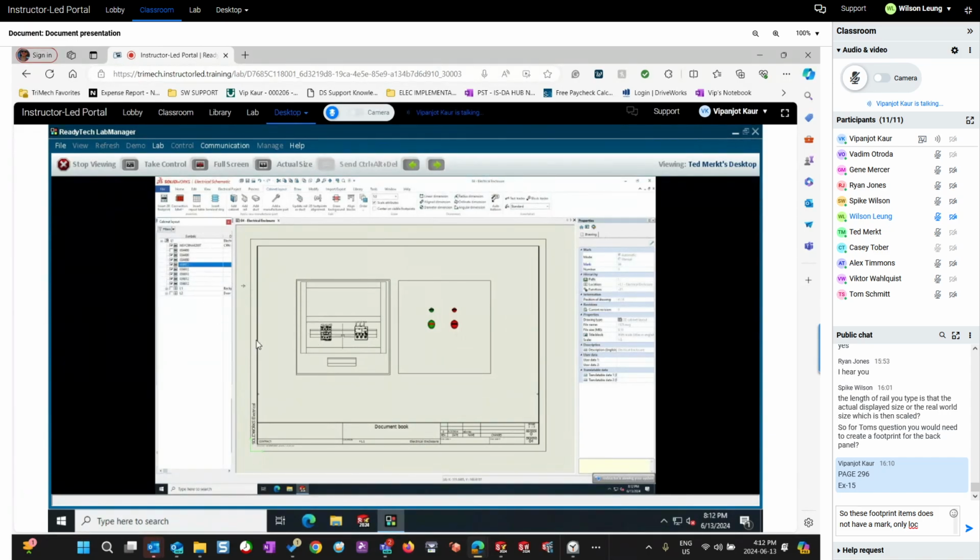Thank you. So step number 3, they're saying insert a rail. So go to part number 034480, second one in the list. Second one, no, this one already has a check mark. Right click, insert a rail. So click and drop it. One click is to drop it. Second click is to resize it.